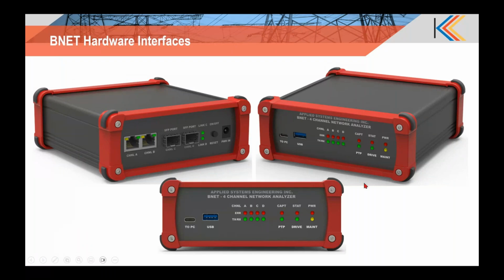You also have channel activity LEDs on there. You've got the error LEDs per the ports. We label our ports A, B, C, and D respectively. And we also have standard indicators for communication, TX/RX LEDs on the bottom half. And then also you'll see the capture LED there, the PTP indication when you have an active connection to your time source, and then a general status LED and drive presence indicator. And then your other standard LEDs are power, and a maintenance LED that indicates that the BNET accessory is detecting connection to your 61850 test set application, which is incredibly beneficial during test time.